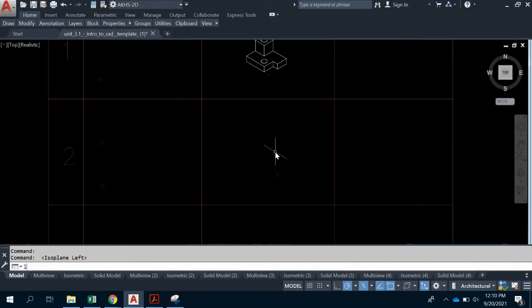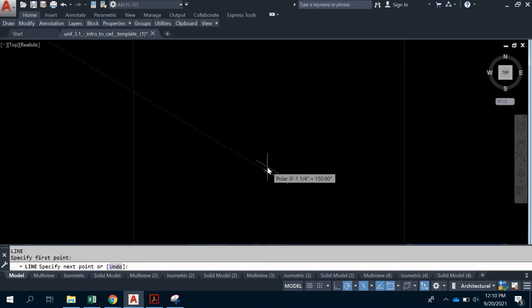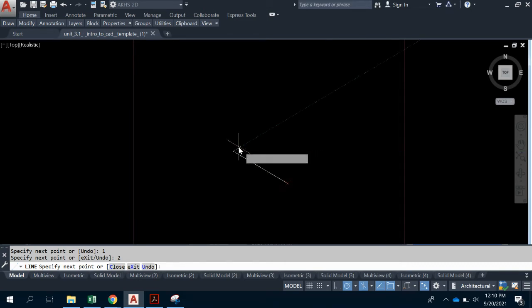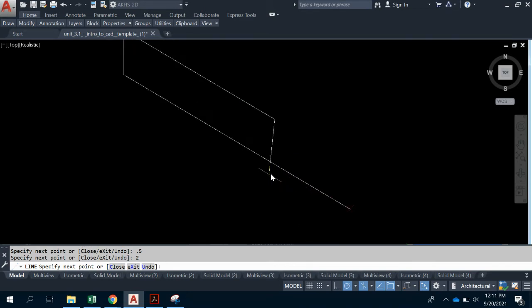All right, so now looking here, I'm going to make sure I'm under the right layer. I'm under object lines. I'm going to draw a line, and I want to go this direction, and I want to go 1, and then I want to go this direction again for 2. Breaking these up into 2 separate lines here is going to help me later, so I can just delete it. So the height of this feature over here on the front is 0.5, enter. We're going to go back down into the right 2, enter, and then bring it here and press right click or press enter to escape. Now I can delete this, so I don't need it anymore.